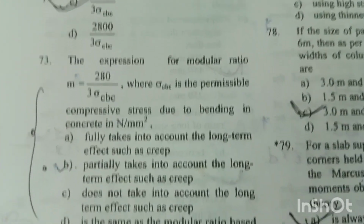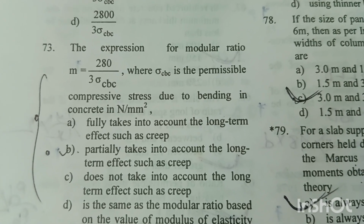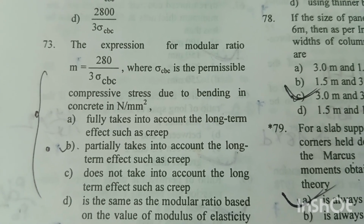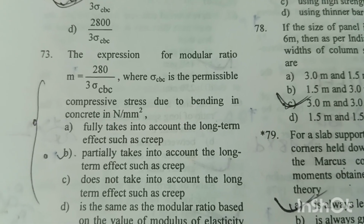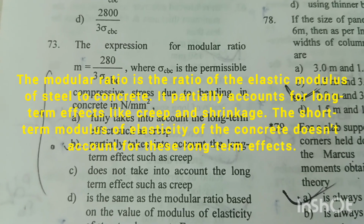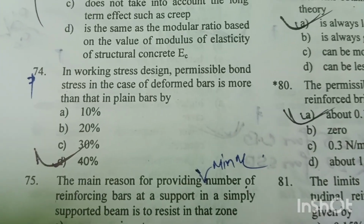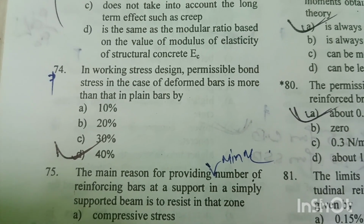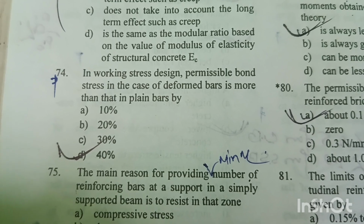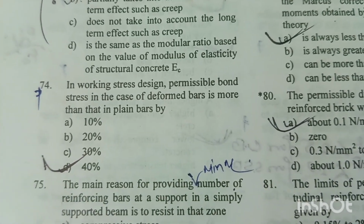Question number 73. The expression for modular ratio M equal to 280 by 3 sigma CBC, where sigma CBC is the permissible compressive stress due to bending in concrete in Newton per millimeter square, partially takes into account the long-term effects such as creep. Option B is right answer. Question number 74. In working stress design, the permissible bond stress in the case of deformed bars is more than that in plain bar by 40%. Option D is right answer.